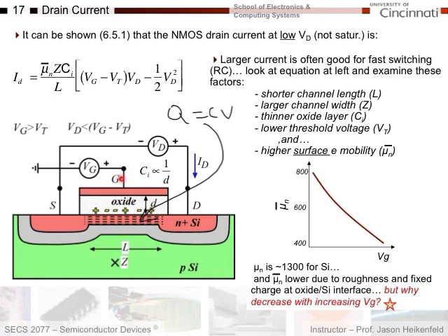Remember we said we have this interface charge here? This is basically where the oxide and the silicon match up. You've got two different material systems with two different types of bonding. And where they match up at the interface, you are bound to have silicon dioxide with an incomplete bond. You're bound to have silicon atoms that don't have 4 other silicon atoms to bond to at that interface. And anytime you have atoms without complete bonding, you always have dangling charges and a net charge of positive or negative. And so right at the surface here, you get these positive and negative charges.